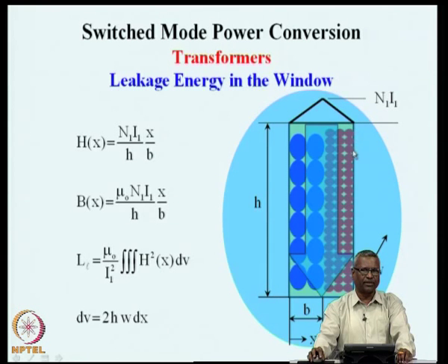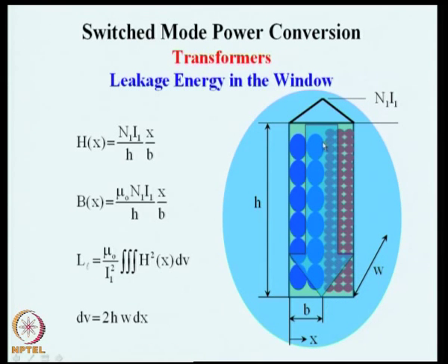The magnetization ampere turns are because of the red winding or primary winding, and the other winding, which is the secondary, is the increasing ampere turns, because as the current is building up, any line that you take from here is enclosing the current that is to the right hand side of that. So, you might say that at a distance x from the left hand side, if you consider a vertical line, it is possible to find h of x along this vertical line.